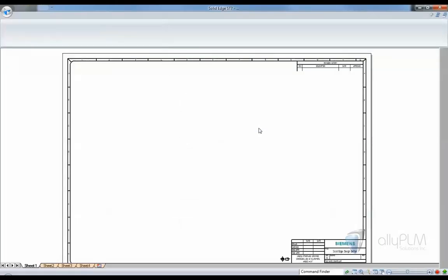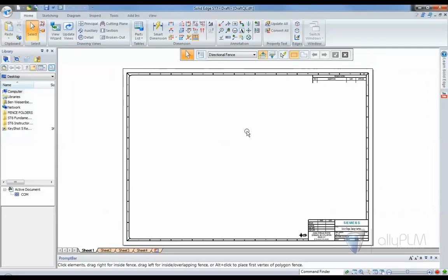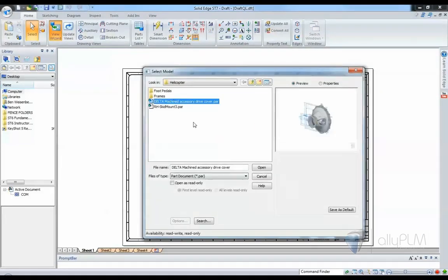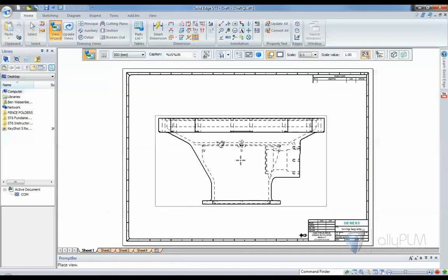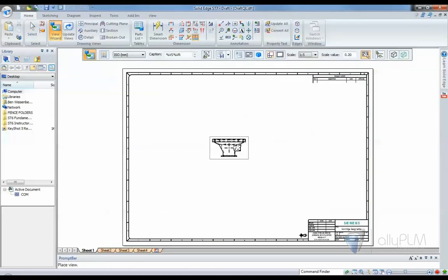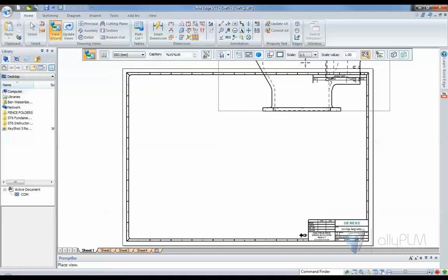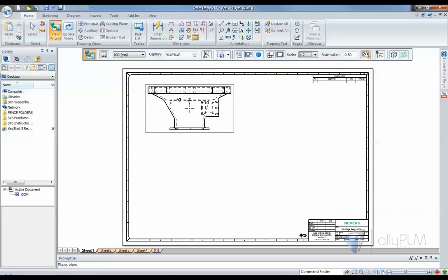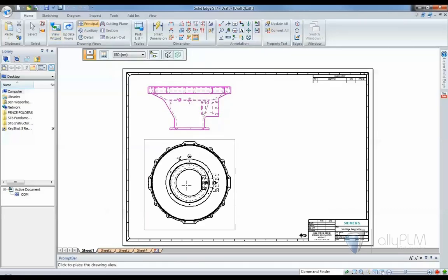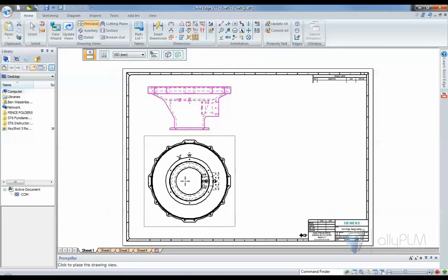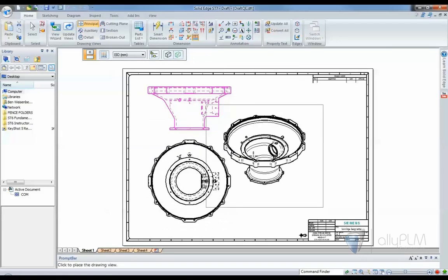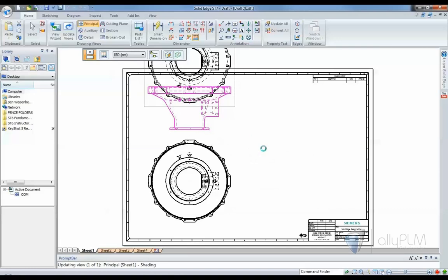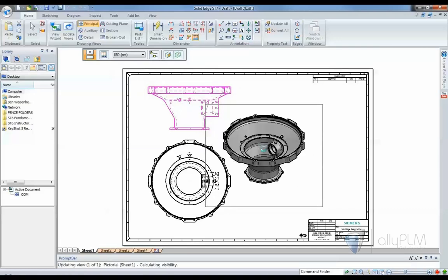We recognize that drawings are a key deliverable for most of our engineers. Our goals have kind of always focused on reducing drawing production time. Solid Edge ST7 continues this by introducing new functionality to minimize time to market. So ST7 extended the dynamic display of drawing views to all view types, including section, detail, auxiliary, and principal views. So we can dynamically create and position several of our standard views here of our accessory drive cover. And Solid Edge also has the capability of shading any view, and now this also can be done and displayed before placing the view, as you see here in our ISO view.